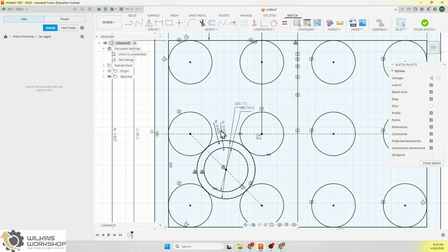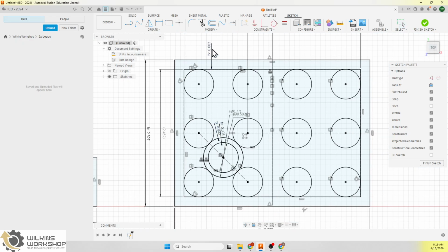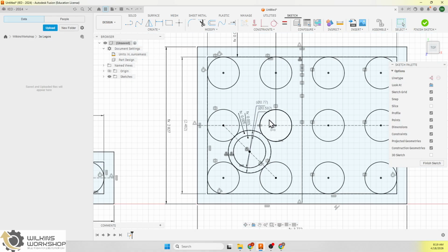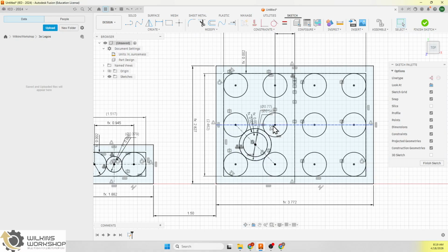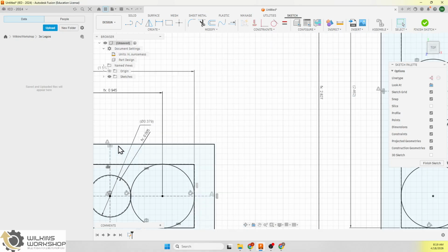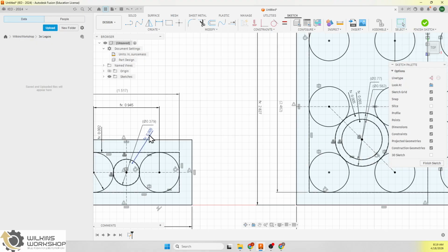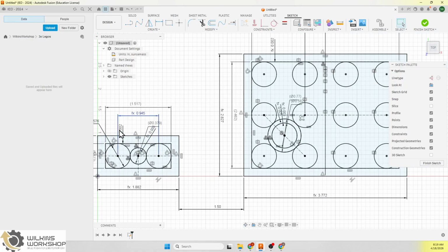So wherever we did these offsets, the reason why I'm leaving them out and open is you might have to make adjustments based on your 3D printer. We're using PLA Plus for most of our parts, and we're using Bambu printers, which are pretty good at being consistent. But this is, like I said, where you're going to want to make adjustments. There are all of these little offsets based on your 3D printer.